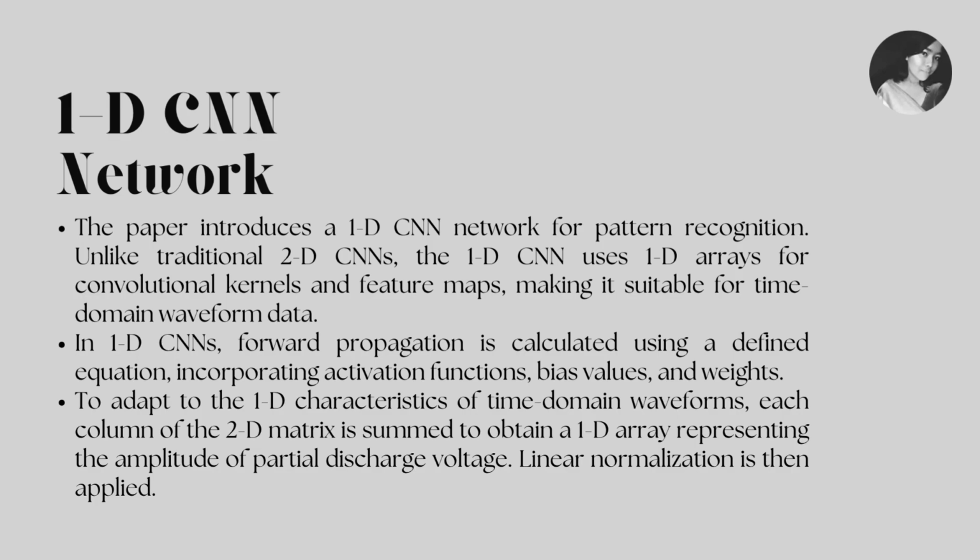To adapt to the 1D characteristics of time domain waveform, each column of the 2D matrix is summarized, obtaining a 1D array representing the amplitude of partial discharge voltage. Linear normalization is then applied.